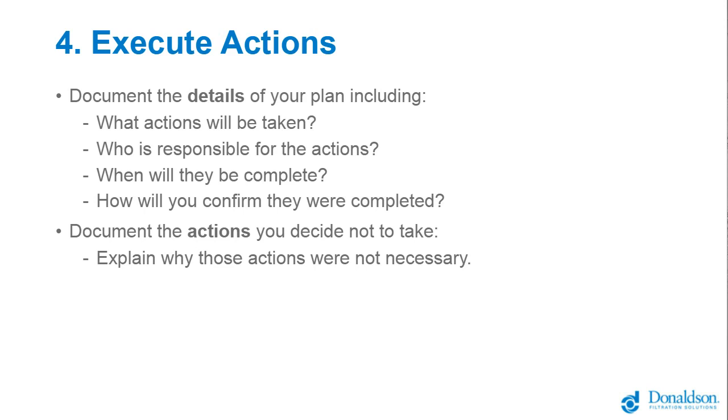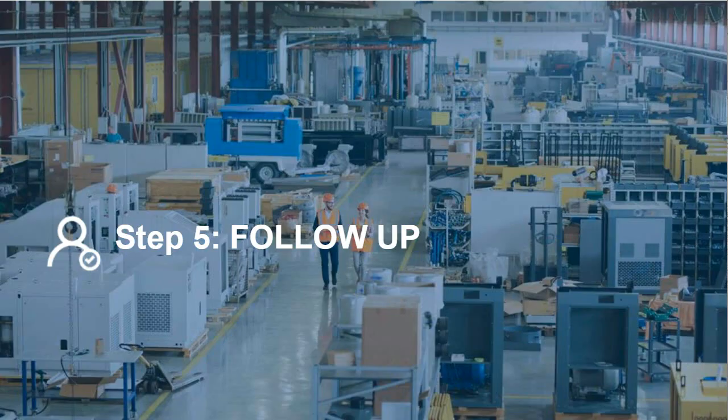And finally, how will you determine if the strategies are effective? Well, the easy answer is the effectiveness is partially measured by the absence of any events. However, certain situations are prone to potentially change and challenge those actions. This includes any change to the process, from a change in the materials you're working with to a change in the equipment and dust collection system layout. So step number 5 of the DHA is to follow up on this living document.